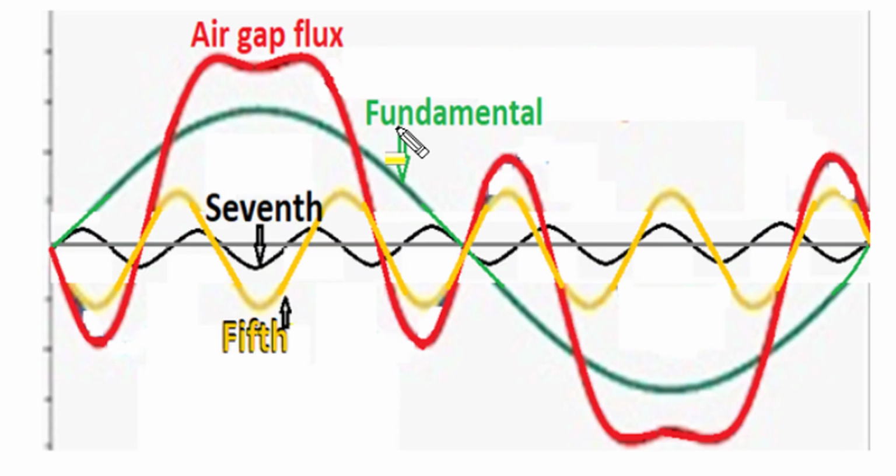If an induction motor is designed in a poor manner, and the winding slots per pole per phase is non-integer, and in the design the number of stator slots and number of rotor slots have an adverse numbering and difference, and also the profile of slot and teeth is such that two adjacent slots produce a low reluctance position and two slots produce a high reluctance position in two nearby space positions, it will produce hooks and cusps of the flux wave, or increments and decrements in the flux wave, and that results in this red diagram, the non-sinusoidal air gap flux wave in an adversely, badly designed induction motor.